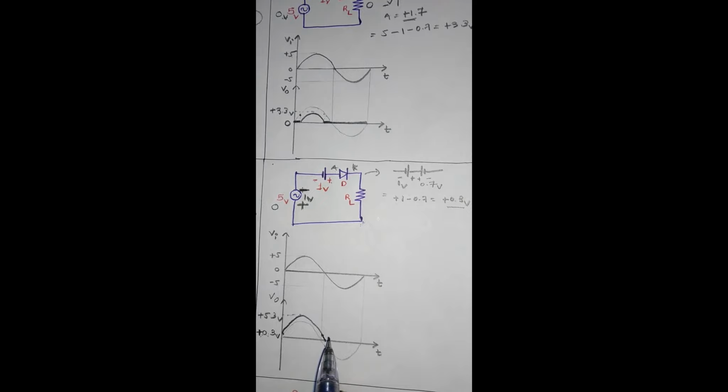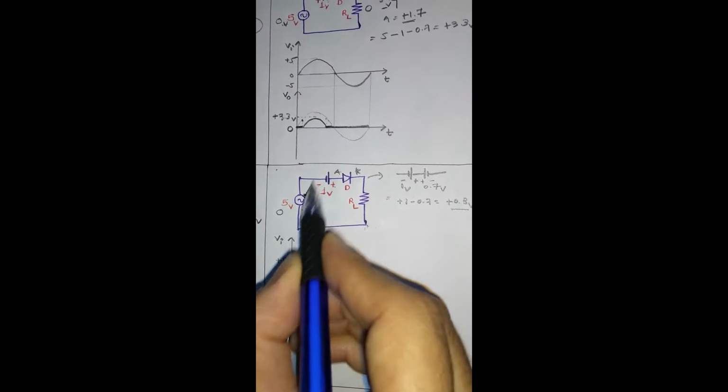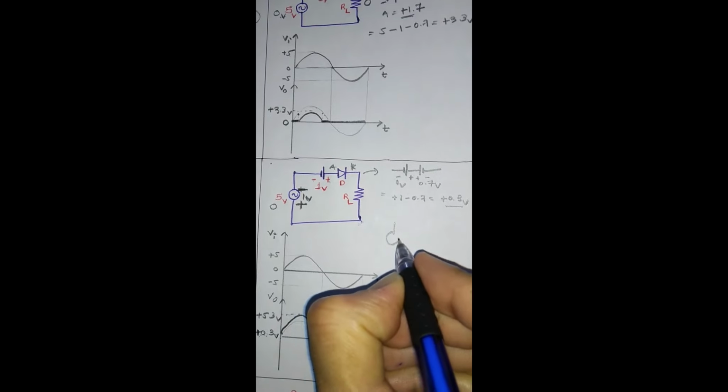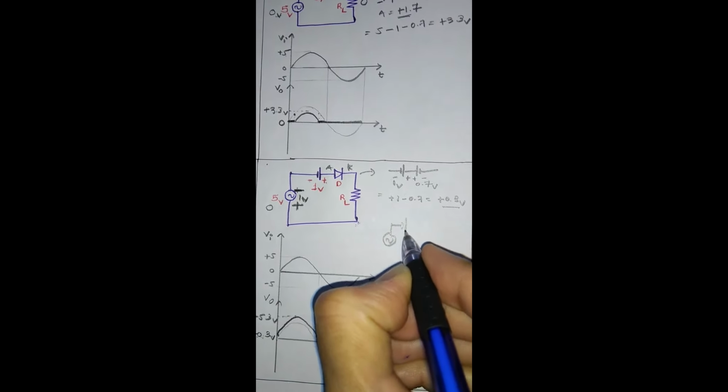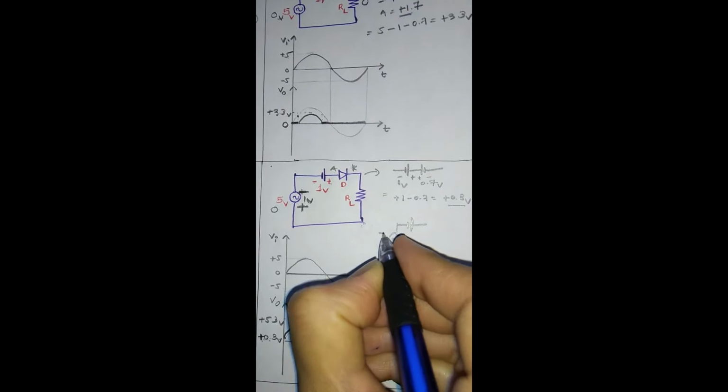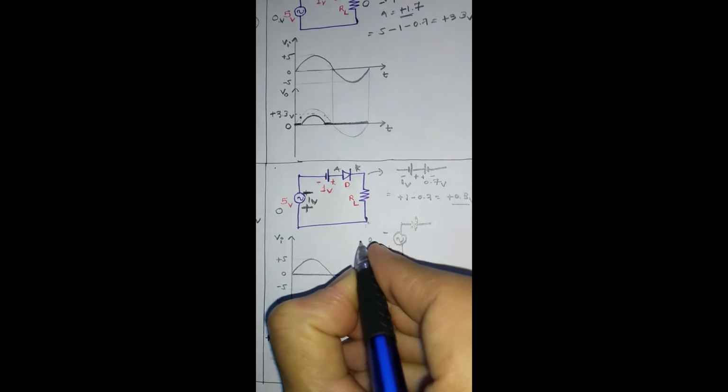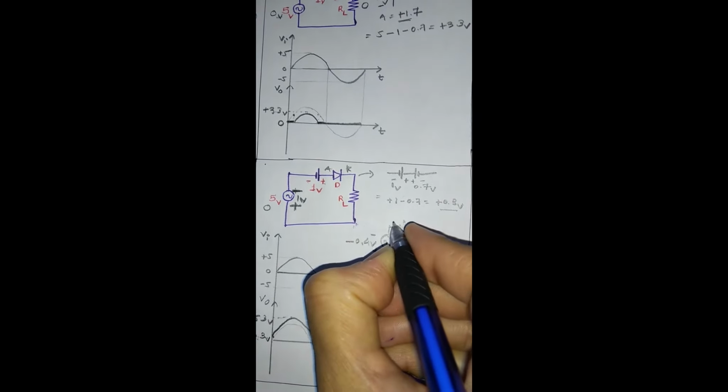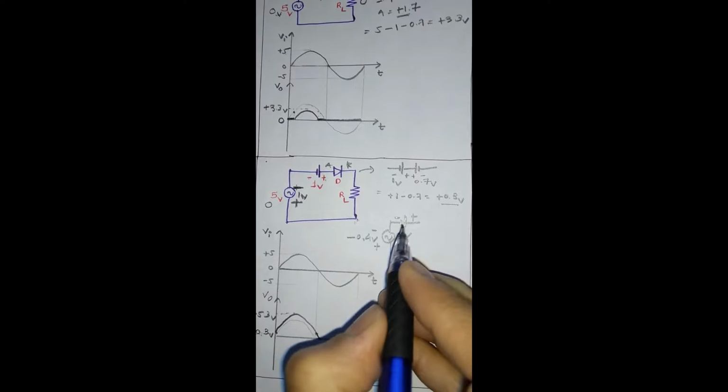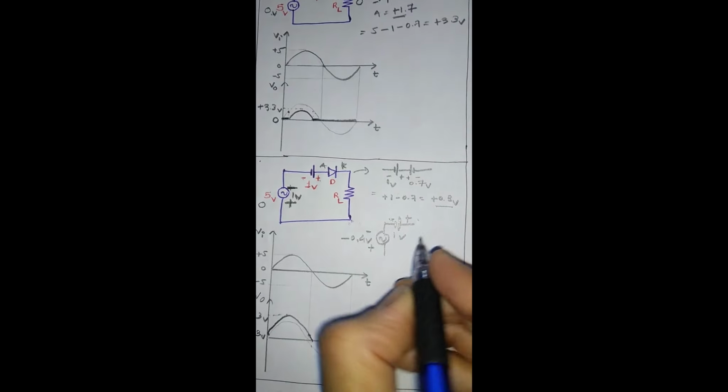So when your diode is off, consider the plus 1 bias supply fixed. So draw the equivalent diagram of the bias supply with input. When input voltage is minus 0.4 and your bias is fixed at 1 volt. So plus minus minus plus. So consider the calculation: minus 0.4 plus 1 is equal to plus 0.6.